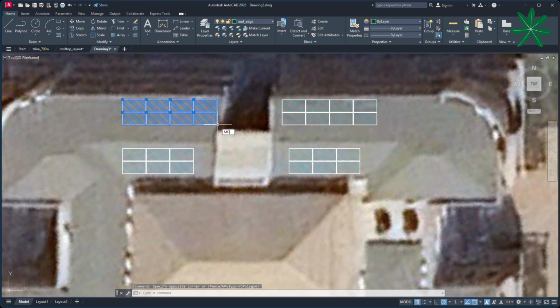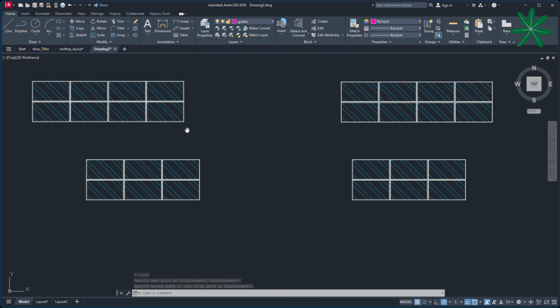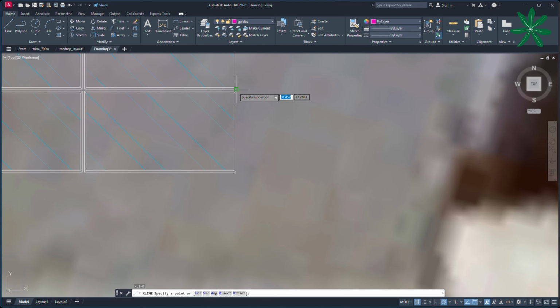Similarly, we move this series a little away from the cutout area. Now that figure casts shadow, so we need to take it away so that it won't cast shadow upon it. You can see that there are still some rooms where we can place a couple of panels. So let's do that. Let's create our grid and attempt to place them there.